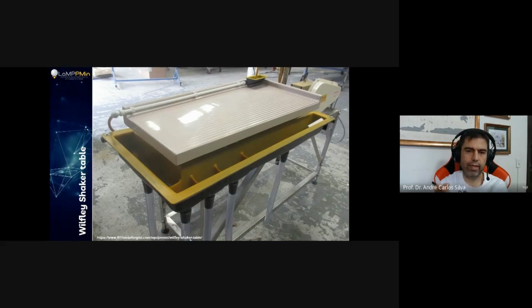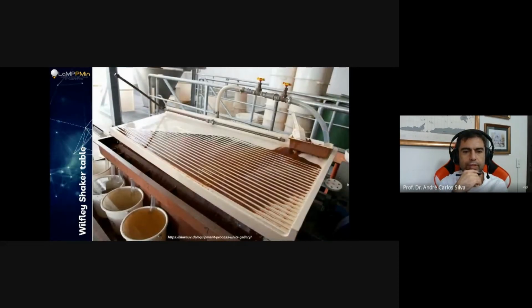works perfectly for gold. Okay, so how this machine works, it's a beautiful machine. We have some pictures like this, so you can have a better understanding. I'm going to feed my material over here in this small area, and in this case this is an almost lab scale equipment. You produce your slurry right over here. The slurry is going to enter the equipment in here, and this table is called a shaking table because it's moving left and right all the time, so it's literally shaking.